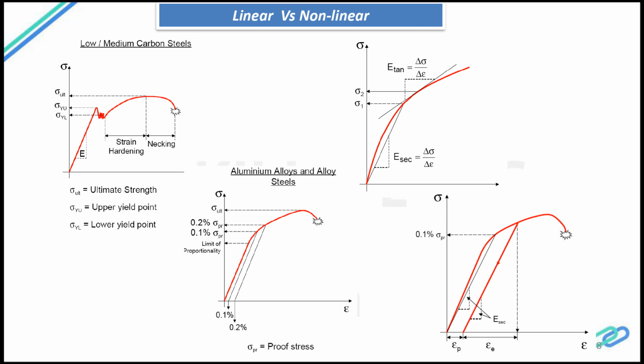And similarly for the plastic regions, the tangent modulus will be calculated, and they will draw a straight line passing through some of the points of the plastic region curve, and then they calculate the tangent modulus, and that will be fed into the Young's modulus.